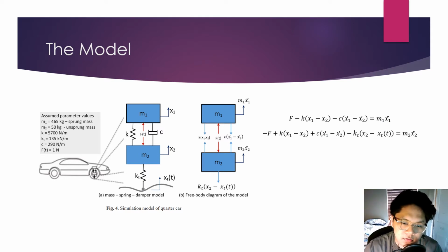suspension system. So, for example, a quarter car specifies 1/4 of the car, so for one wheel, and there are four wheels, so this is 1/4. So we're able to come up with this model for the mass, spring, and damper model. We have the first mass, the sprung mass, the second mass, the unsprung mass. Then we have the spring connecting those two and a dash pot.